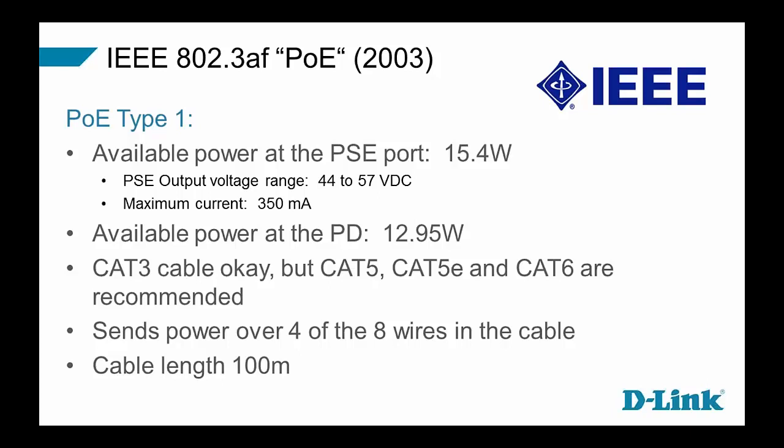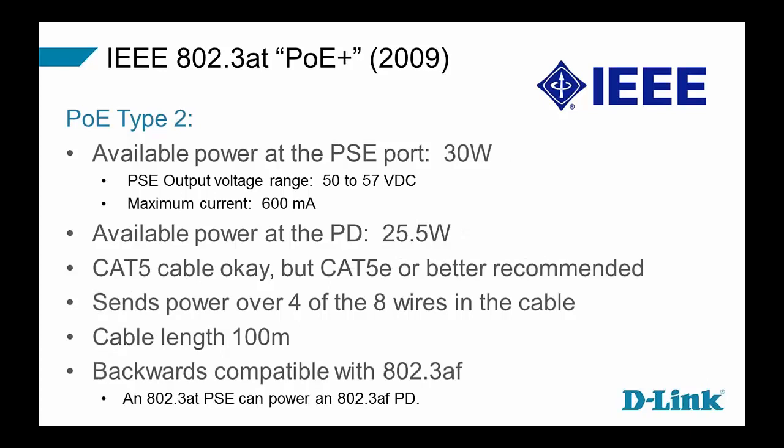So we'll talk about this a little bit more in an upcoming slide, but it's important to recognize here within that 4-pair LAN cable, 2 of the 4 pairs are carrying the DC power. And because this is 802.3 Ethernet, we're supporting cable lengths up to 100 meters.